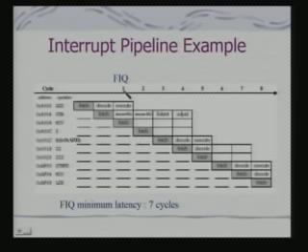So, if FIQ occurs, you actually go to 001C, which is the vector. At this vector you have a branch instruction, and you are branching to AF00. When you branch to AF00, the pipeline has to be flushed again. You go to this location and start execution of the first instruction of the interrupt handler. So, effectively what we are seeing here is that the minimum FIQ latency is 7 cycles. This is a typical situation.